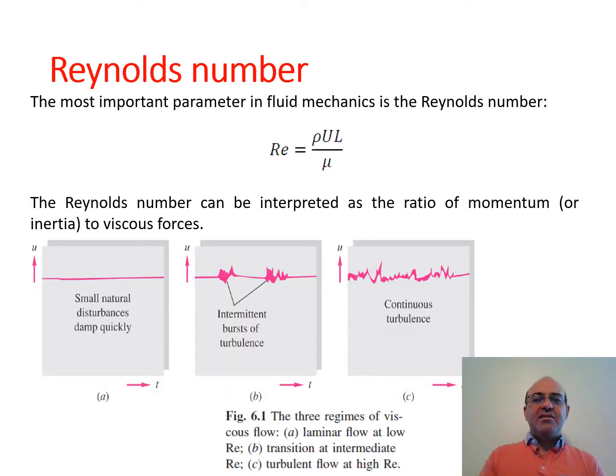So let's go back a little bit as a refresher. We had in the previous chapter the definition of Reynolds number. Reynolds number in fluid mechanics is the most important non-dimensional number. It is density, velocity, a characteristic length. For a pipe, the characteristic length is usually the diameter, not the length. So if we show it as Re_D, then it means that this L is equal to D. So density, velocity of the fluid, characteristic length, diameter, divided by the viscosity of the fluid.